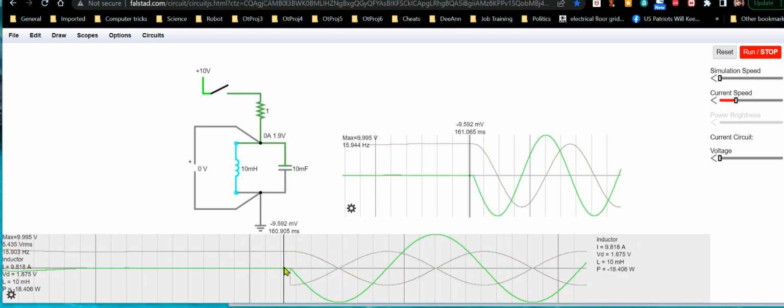But basically, in this first cycle, the inductor is discharging while the capacitor is charging up. And again, once the capacitor's current reaches 0, that means its voltage has peaked. Okay, that means the capacitor is fully charged, and because the current of the inductor is 0, that means the inductor is fully discharged. And the same as the capacitor, it's got 0 current, so again, it's at 100% charge with a capacitor, because that's what you would expect with a capacitor. It has a voltage in it but no current, it means it's charged.